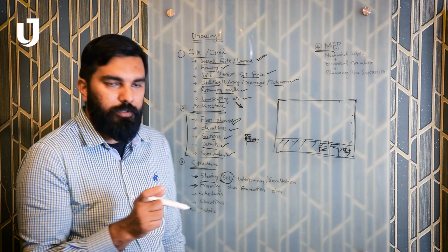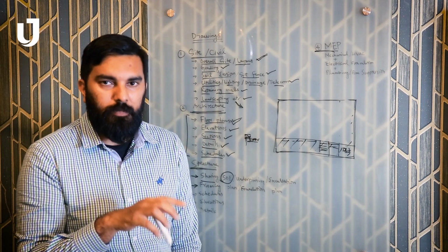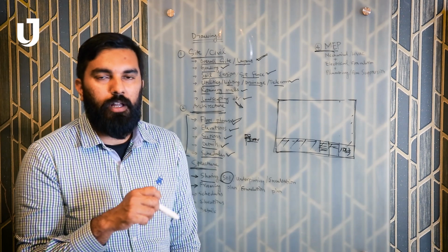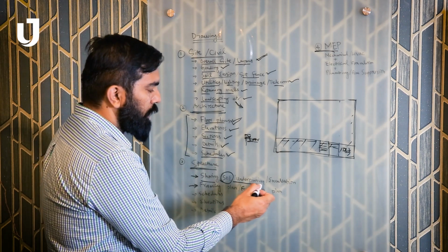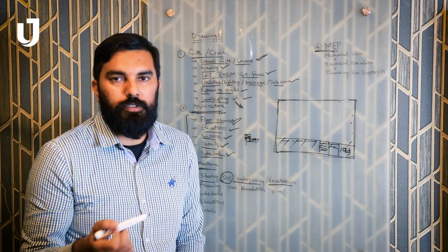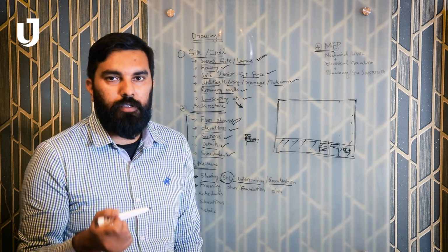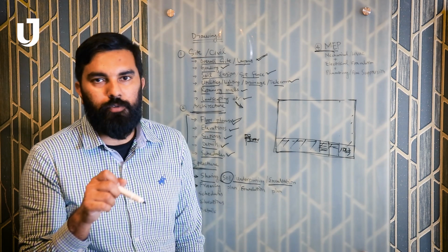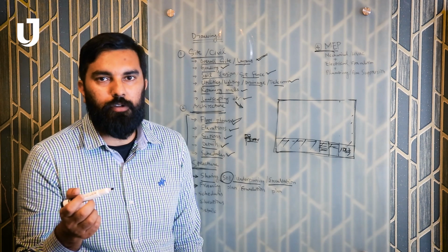Then, if the foundation of the adjoining building is above the foundation of the new building that you're going to construct, we'll have to do the underpinning in that particular portion. So we can have the underpinning drawing. Then sometimes, depending on the details of the architect or the engineer, they can provide you with the excavation drawings saying you have to do the excavation with this much slope in this area, and you have to do shoring where the excavation or slope is not possible.